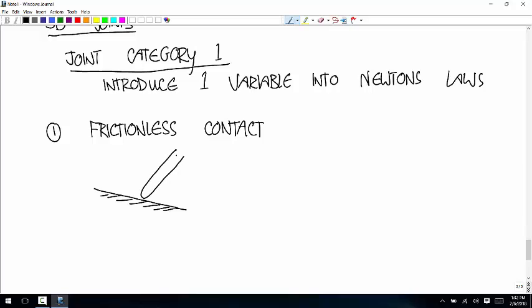If you have some object that's just in contact with a surface, I'll think about what that contact looks like. So if this is frictionless in its contact with the ground, the table prevents it from translating down into the table. So there's something going on there, right? That's one direction of force. But it still can translate along X, along Z, or however you have the thing oriented.